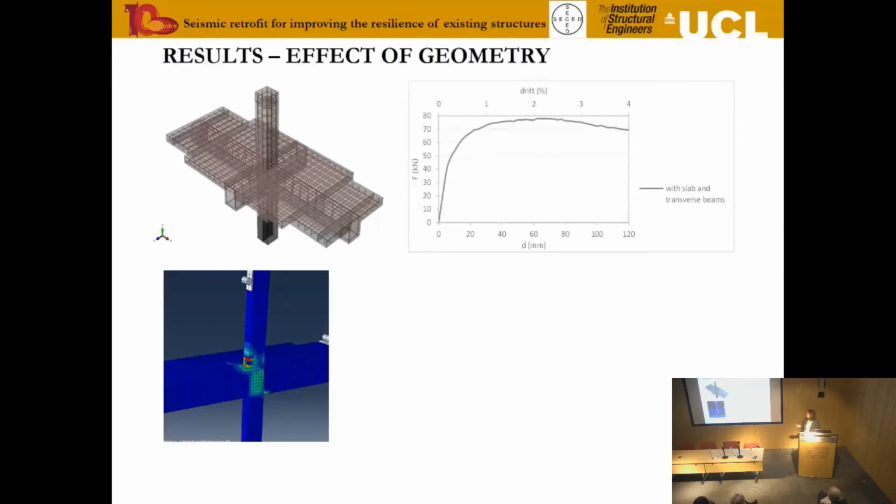It's very much concentrated in the top column. It's what we see in the field, so it's sort of expected, yes? It's this column failure with some level of damage within the joint. What we see is quite a high strength and reasonable ductility, but not very high.